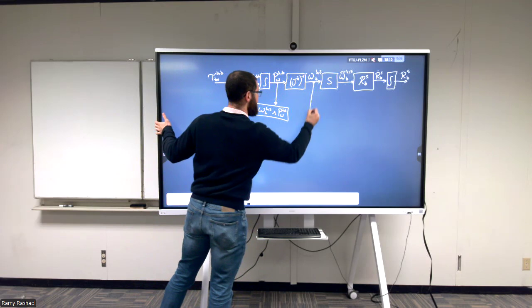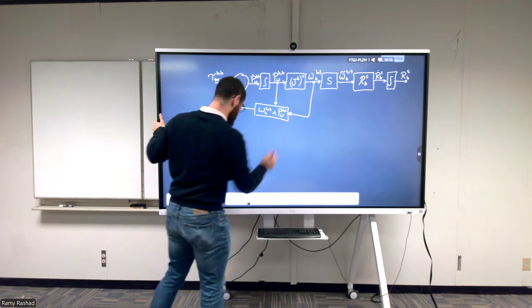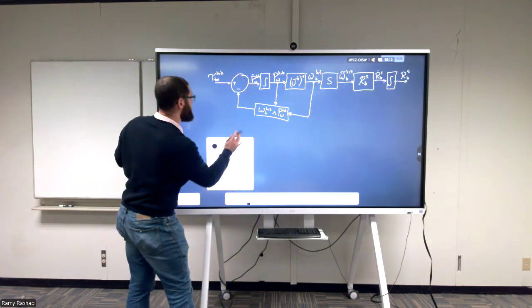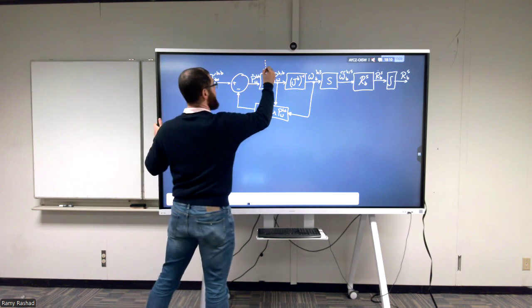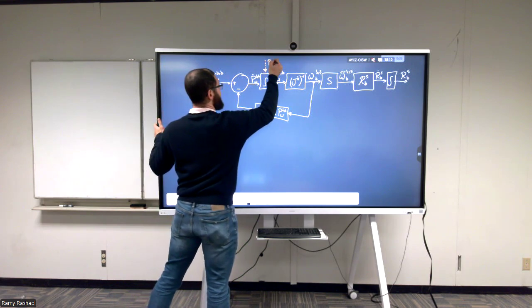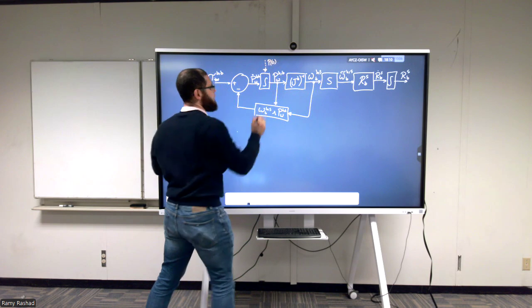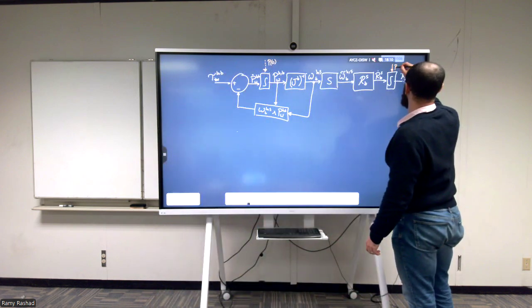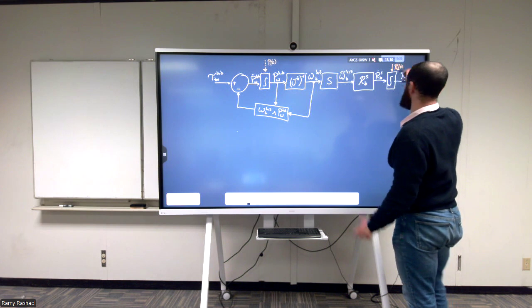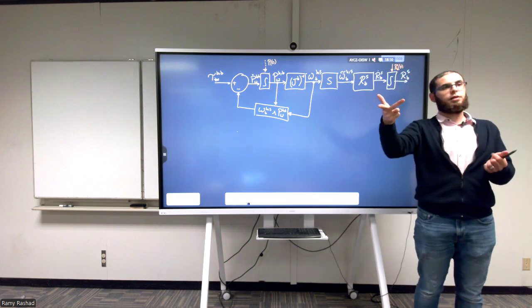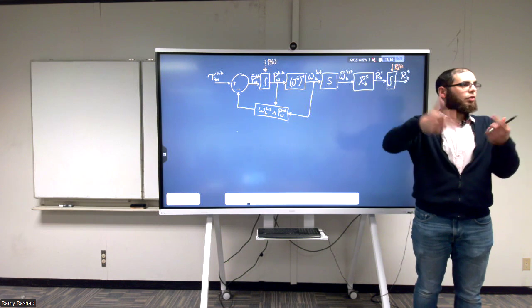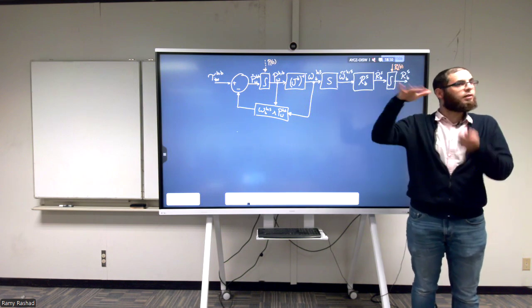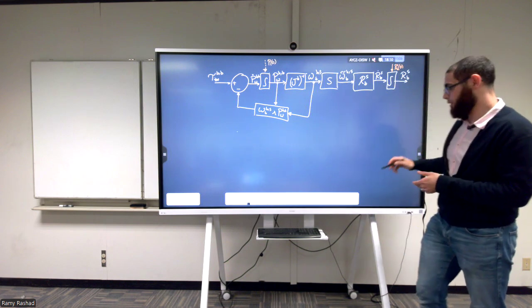And of course, let's not forget that I need to provide the initial conditions, which is the angular momentum at time 0. I also need to provide the rotation matrix at time 0, which is the initial orientation I started with, and the initial velocity or momentum I had when starting this simulation or time integration.